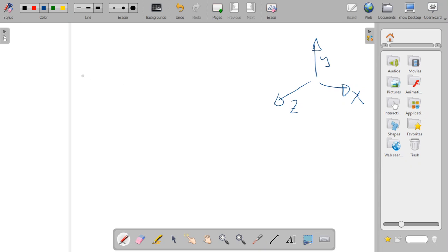Okay, and again, for example, I have a member and this member is in the x direction, the same direction as this member, so this is my x. The loading is in the z direction, and this is my load, 1 kip, in the z direction. This is 10 feet. If you rotate this 1 kip towards this support, it forms a clockwise moment. This is clockwise, so I have to apply a resistive moment.